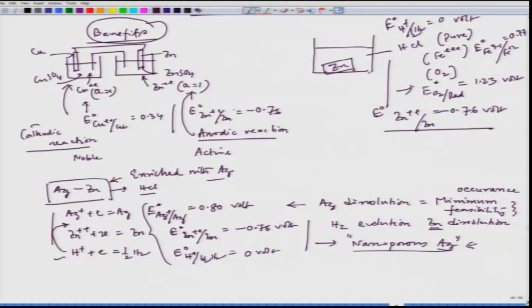So, this is highly active; this zinc would behave actively, and the other three reactions have higher standard reduction potential. So, we can make out that yes, zinc would dissolve and there could be the possibility of all those three reactions, and that would actually increase the zinc dissolution rate or zinc corrosion. So, this information we can also snatch out from this.